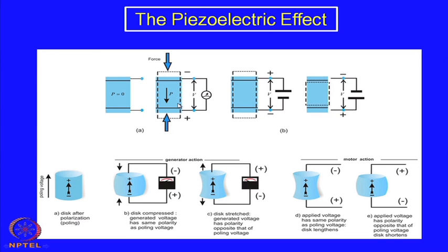That is the difference between normal dielectrics and piezoelectrics. This is also a dielectric material, but of a different nature. This also has a spontaneous polarization. The only thing is that they are much more sensitive to mechanical stress. So, by applying a mechanical stress you actually polarize it, and that polarization comes up in the form of a voltage.